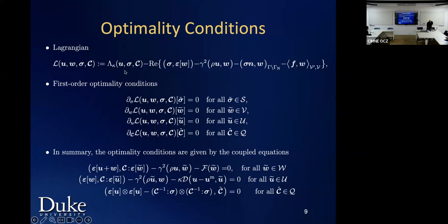So this is my Lagrangian here. This is the only thing I know: the fundamental governing equation, conservation of linear momentum in this case. For now, you could impose other constraints on these fields, but let's not do that for now. So this is a problem that is basically enforcing the governing equation. Take variations with respect to each of those, and you will get this system, this coupled system of variational problems. The first one that you see here looks like my original wave propagation problem, except that I have the Lagrange multiplier in it as one of my variables.